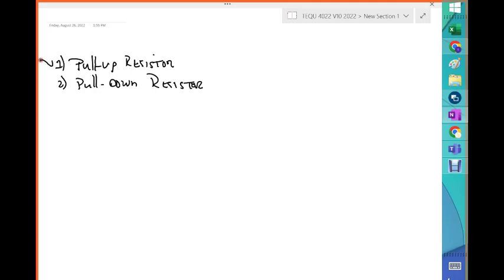How do we set the pull-up resistor? The pull-up resistor is basically set up as follows. I want to have 5 volts, a resistor, a point, and a switch. There we go. This resistor is going to be a 10 kilo ohms resistor. And this is the line, or the wire, that eventually will go to the Arduino, to the pins that are declared as inputs.